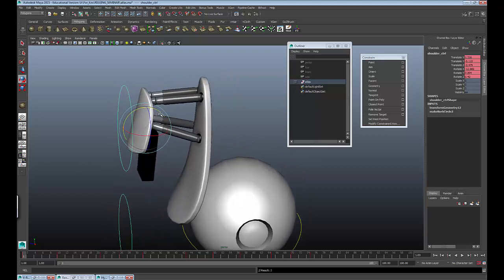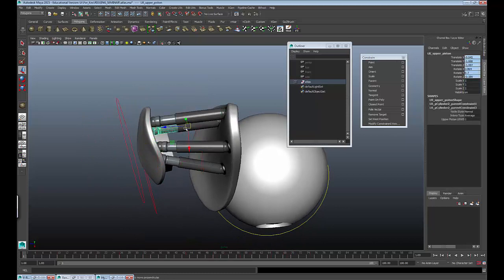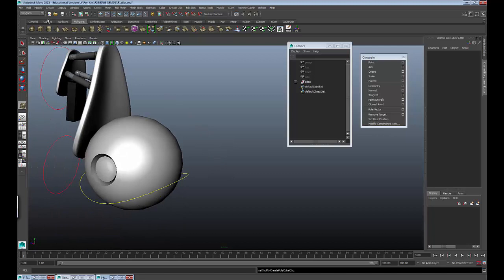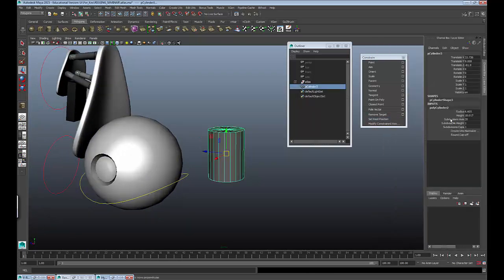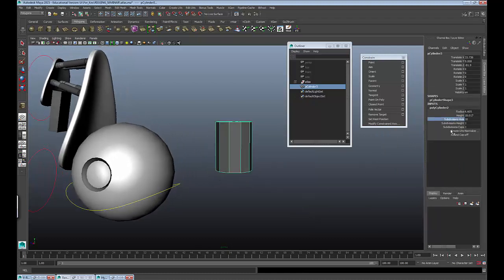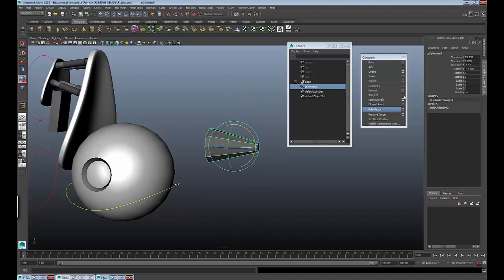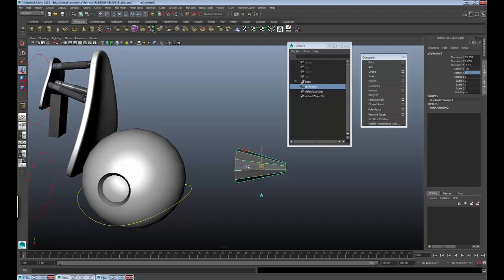So what we could do is create a situation where these piston shapes exist outside of the hierarchy of both the arm skeleton and the body skeleton, and basically use both sides to drive various components. So let's take a look at this, just as a little bit of abstract perhaps. I'm just going to start by creating a very basic shape here, and not necessarily a piston, but let me just reduce this down a bit. And freeze transforms, delete history, okay.